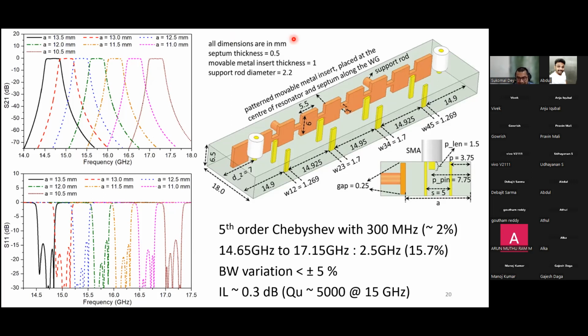So it is basically connecting to the question one of the participants asked, that is the vibration effect. Related to that, you said that you will add one λ/4 line and connect it to the RF choke, right? I was wondering, this is the open end, so the open end will become the short end with the λ/4, correct? No, I have to add a λ/4 choke with the short end. Okay, then it makes sense.